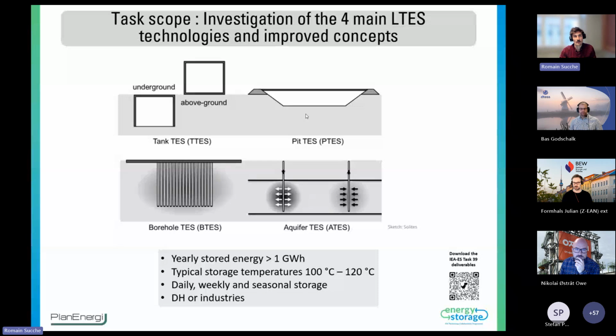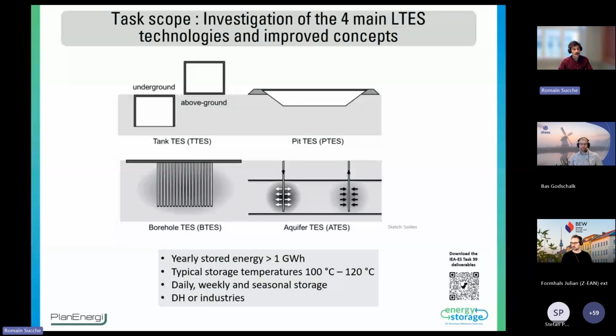The one main characteristic is that we dig soil out and we put it on the side, so that we keep a soil balance. Then there's the borehole thermal energy storage, where we basically use the soil and the ground to store heat, and then the aquifer, which is based on, as it says, an aquifer, so the soil underwater, underground.